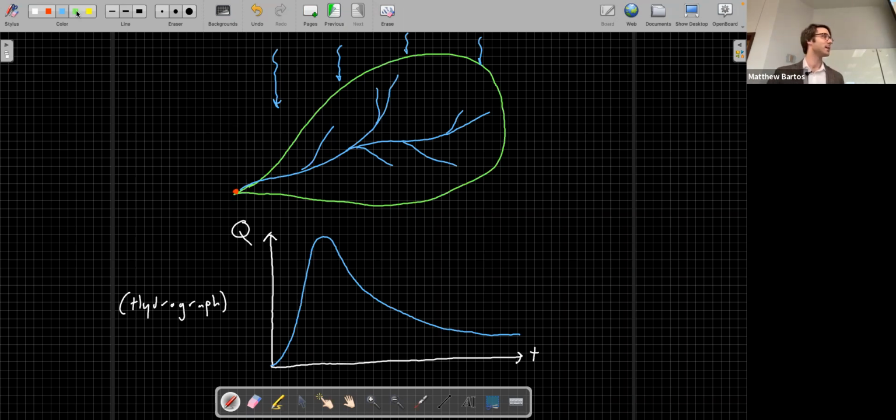when they arrive at the outlet. So let's say we have some raindrop that falls on our watershed and it lands here, right in the channel, very close to the outlet. Okay. This will manifest in a very early part of the hydrograph, right? So this drop of water will end up somewhere right here, very early on in the hydrograph.